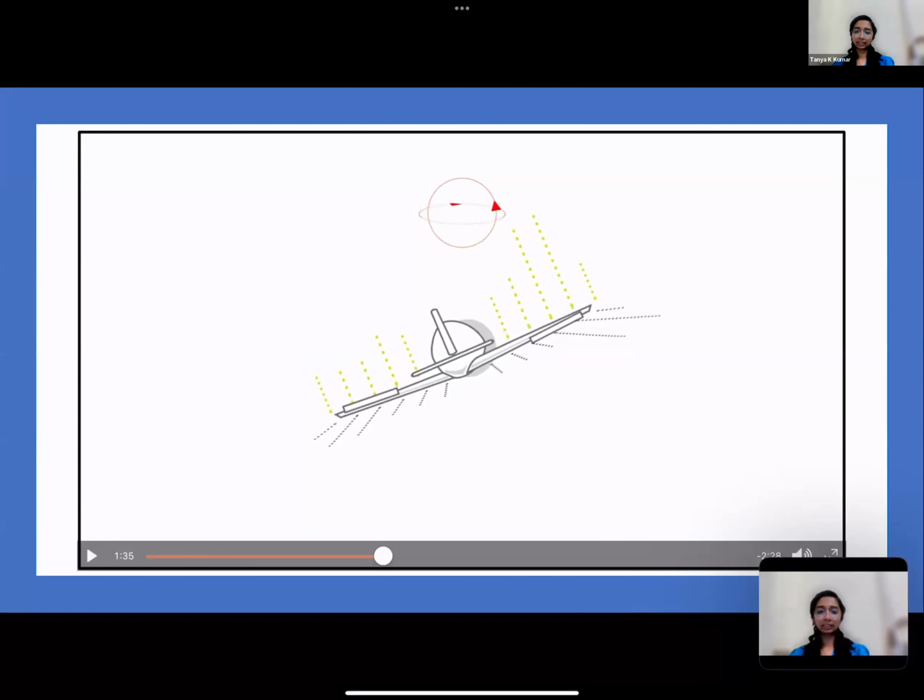This is exactly what Sandra said. The drag on the opposite wing is what she said, but it's like the uneven distribution of the drag forces. When the lift is also changing, drag is also uneven. So when you roll towards one direction, because of the uneven drag, it yaws in the opposite direction, which is not what we need. We don't want our aircraft to roll in this direction, but turn in this direction. Okay. So now they go on to tell another reason, but let's just continue watching this video.